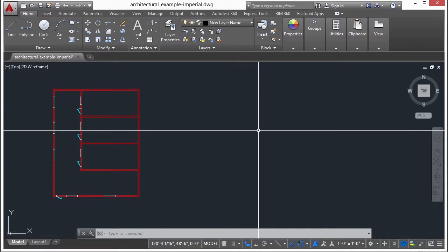And on the same note, you can also change things like color and line type by viewport only. That way you can make a construction line, a solid line, show up in one drawing, but then make that a hidden line in another drawing without having to change your drawing objects.